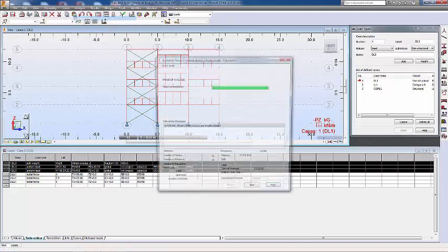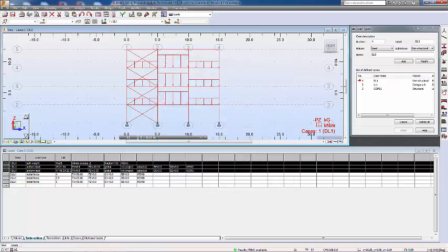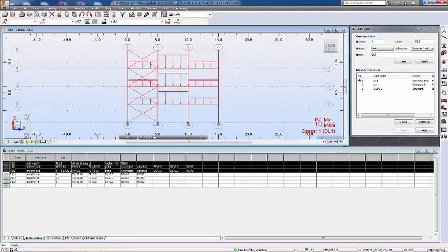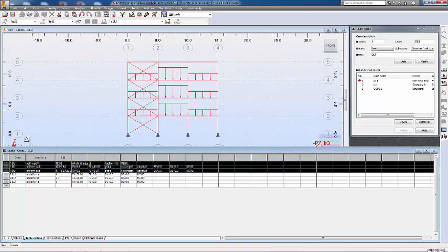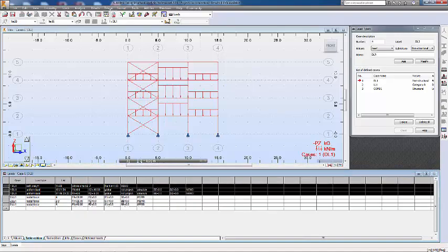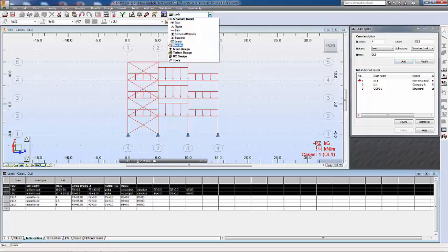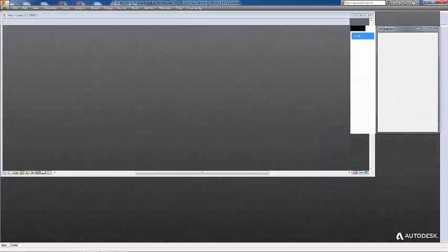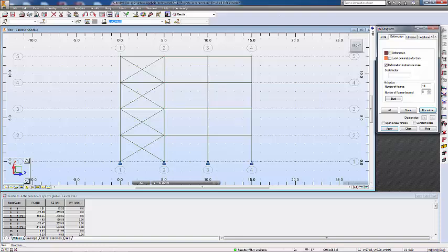Just click on calculation, and then there's no errors. That's great. So let's maybe have a look at the results. So let me bring up the results layout. Let's click on this one and go to result, and then click on this one. So let's have a look at the deformation, and then we can use the first the scale to have a look at the lateral one. So the lateral loading, you see the scale 100 that we're going to use in here.